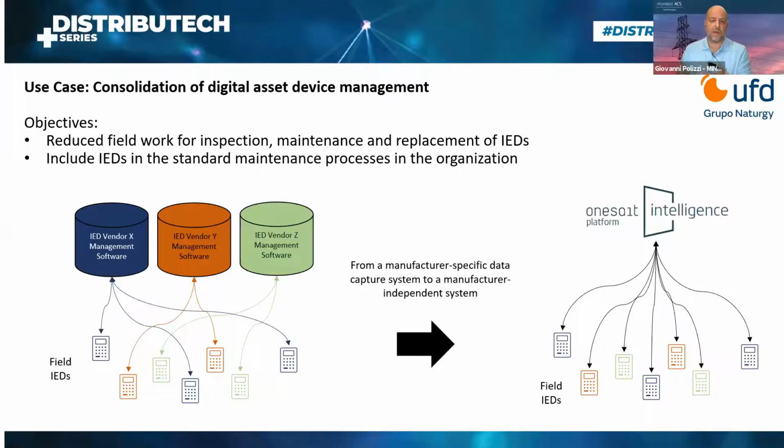So what is the way of making that maintenance or the inspection more streamlined? Of course, the problem that they had is that when we talk about IEDs, we talk about different manufacturers, and different manufacturers give their own flavor to protocols, to interfaces. So it was becoming difficult for them to put the maintenance process for those IEDs within a company-wide application, a company-wide system, and they were always tied to different manufacturers. So they said, okay, let's see how we can start to monitor and inspect those devices by using one single platform.